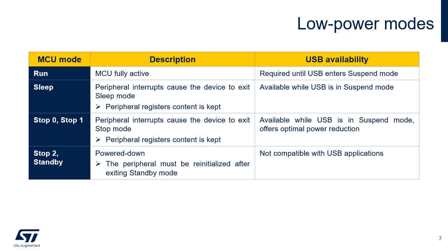In run mode, the USB peripheral remains fully active. After a suspend event, the microcontroller can enter sleep mode, as well as stop 0 and stop 1 modes. Stop 2 and standby modes should be avoided.